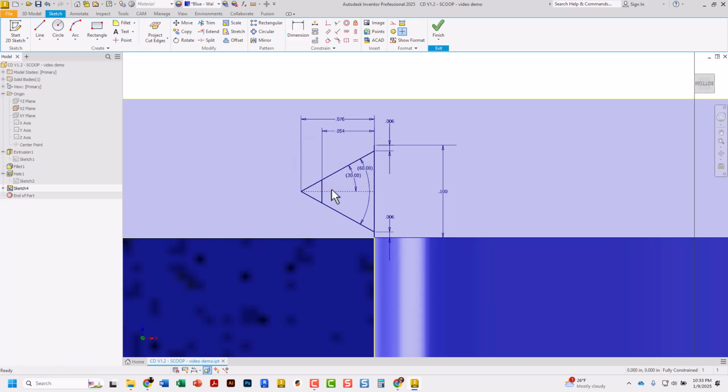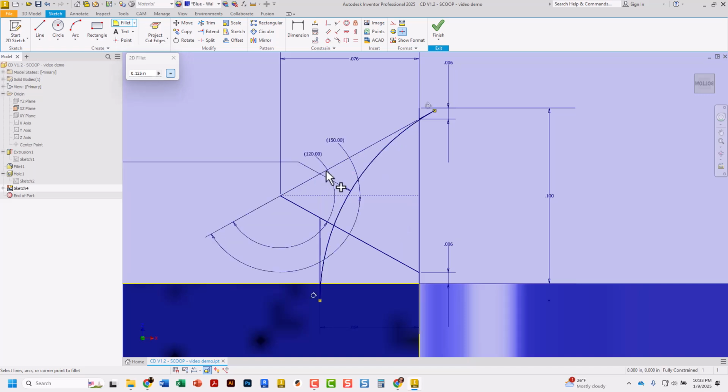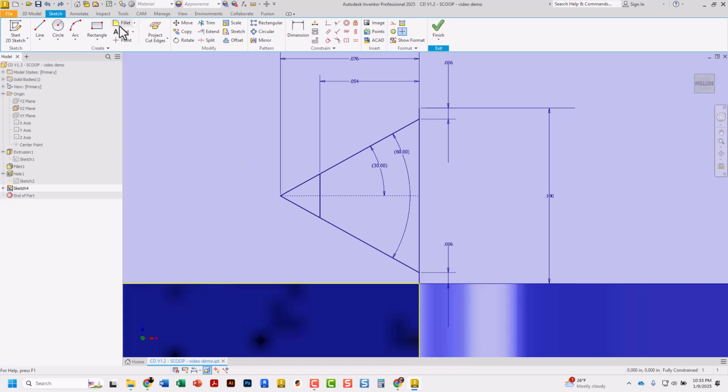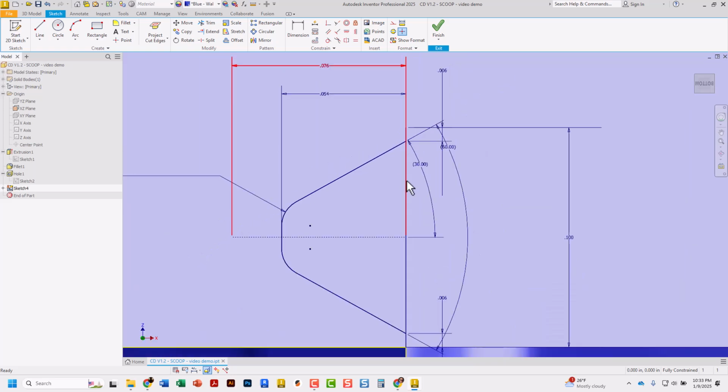And at this point here, I can do a couple fillets. The fillets on this end, oh, just kidding. Let's escape, Control Z. Let's try that again. Sorry. Fillet. You gotta look and see what is in the box there. We got 0.0125. Even happens to me. I always double check that. 0.0125, and then we can click these lines. Both sides. Looks good. Now I wish we could do the same up here, but we need to add a fillet without getting rid of this line.